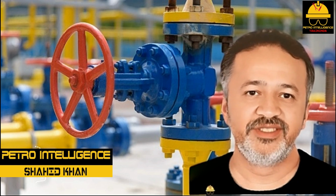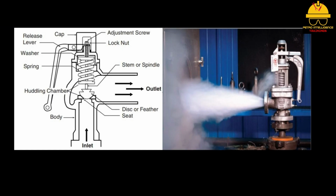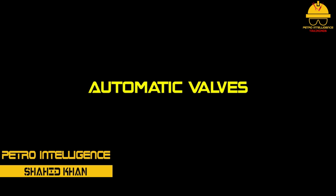A safety valve consists of the following components as shown in picture: a cap that protects the adjusting screw, the lock nut, and the internal components of the safety valve, a spring adjusting screw and lock nut, a casing or body, a spring and two spring washers that hold a constant tension against the disc, an inlet and a large outlet, a disc or feather and disc guide, a spindle or stem that is threaded and screwed into the flow control element to guide vertical movement of the disc, a seat, and huddling chamber, an adjusting ring and ring pin, lifting levers, and pivot pins.